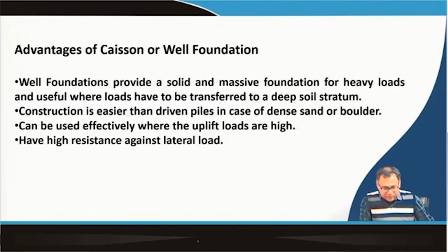So, next I will discuss the well foundation. This well foundation is sometimes also called the caisson foundation. The advantage of this caisson or well foundation is that it provides a solid and massive foundation for heavy loads and is useful where loads have to be transferred to a deep soil strata.